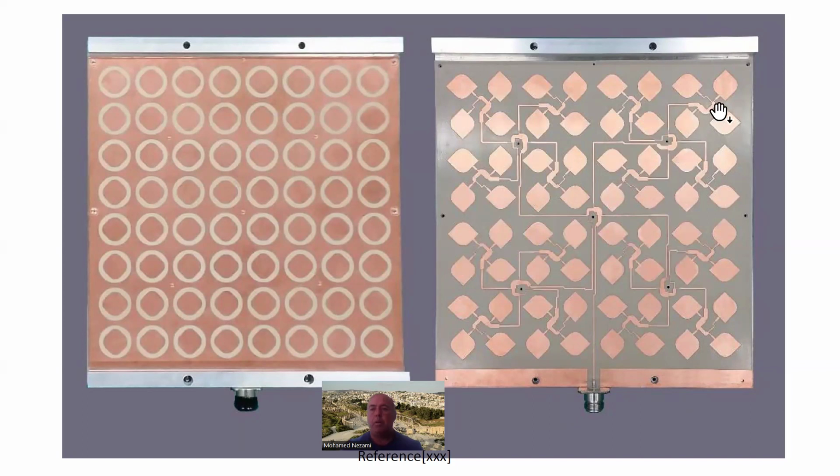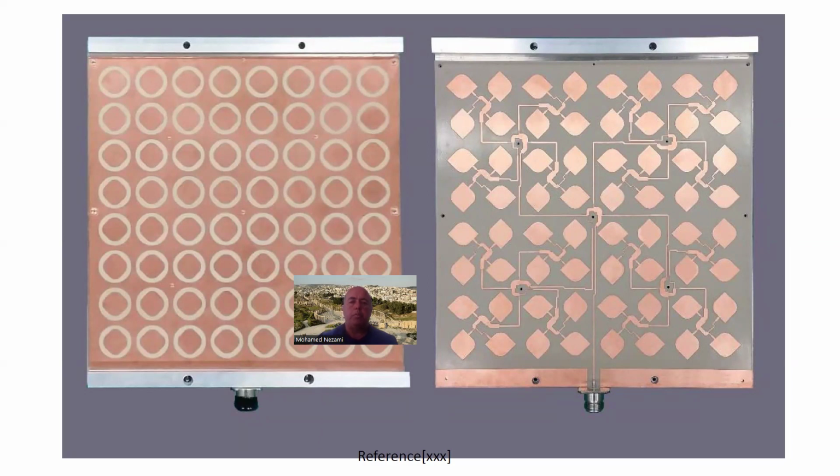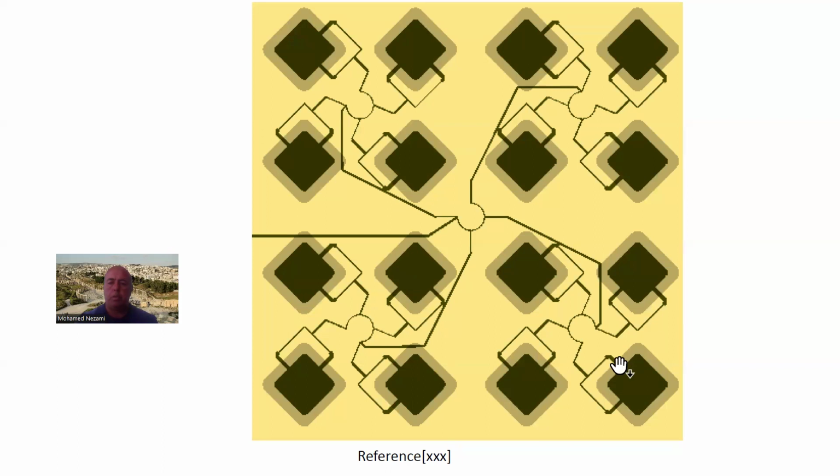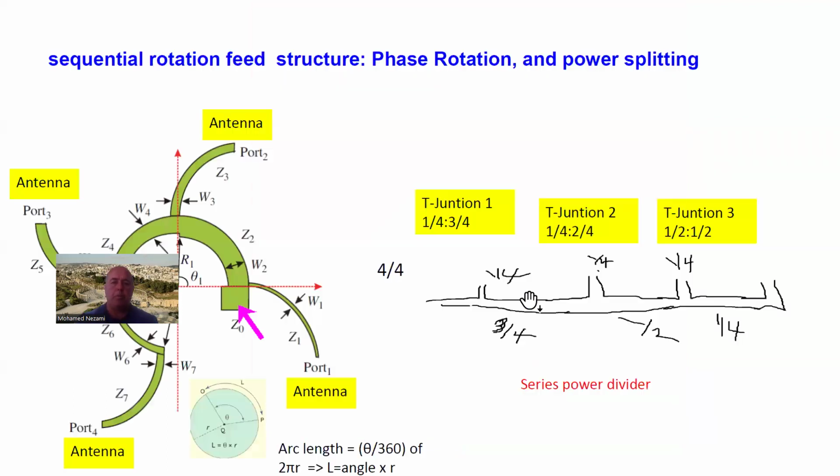Okay, the same thing is done with 4 elements. And these, of course, look funny, but these are corner-wrapped, cornered square patches, which is for circular polarization. Another example that I saw in the literature, of course we come in here, we rotate, and then we do that again. Although with this one I see there's an issue here. This is shorted to this. I don't know whether these people realize. I hope they didn't fab this, but this is just an example from the literature.